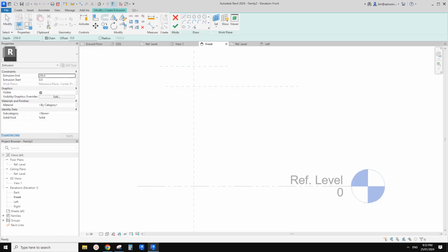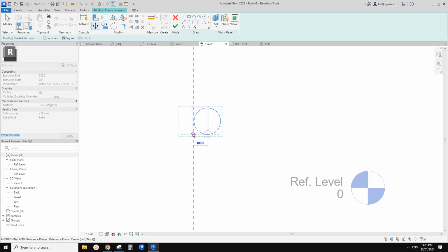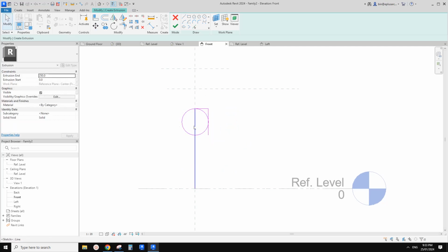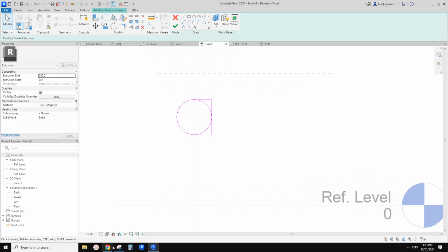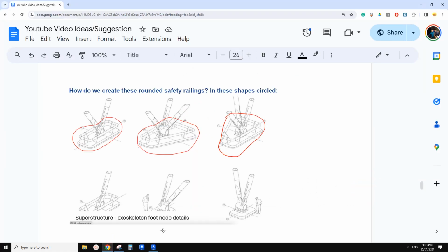So we're going to draw an extrusion. Extrusion and then sketch line. I'll just draw a line up 600 first, and now 200 diameter, so it's like 200 down. Then I'll draw a circle here and move it to here. So this will be the location of this bit.